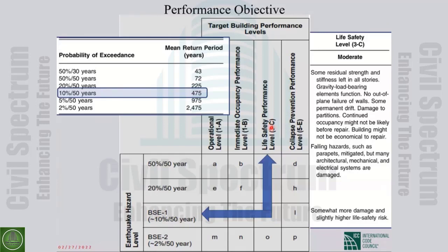We adjust them, somehow modify them, because our methodology is linear, but the real behavior is non-linear. And then we check with the acceptance criteria. The acceptance criteria for the linear analysis will be that for force control elements, none of the force control parameters should exceed the lower level strength. Lower level strength.